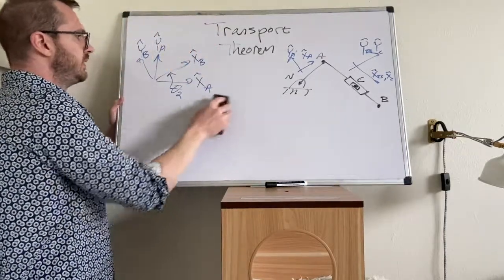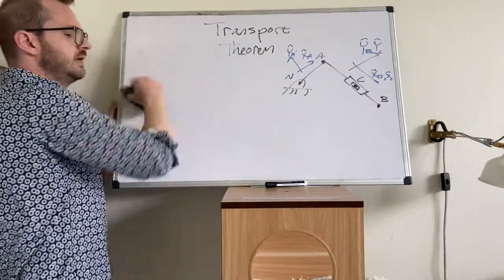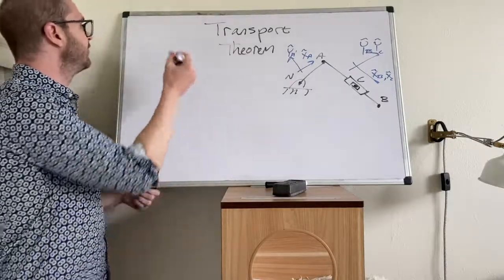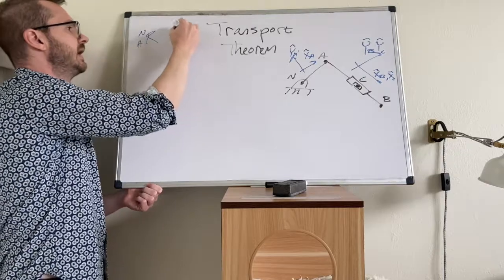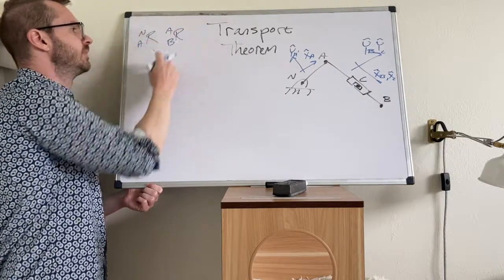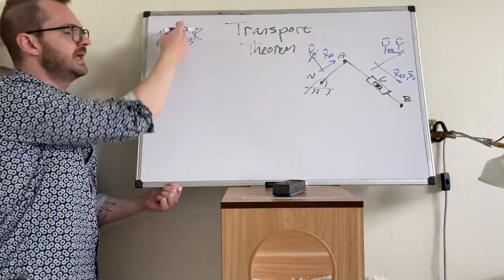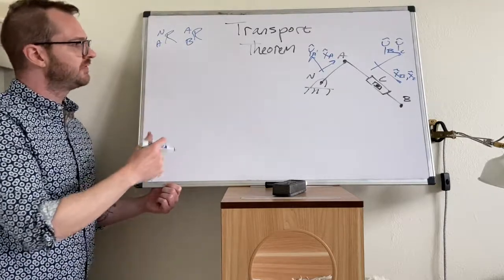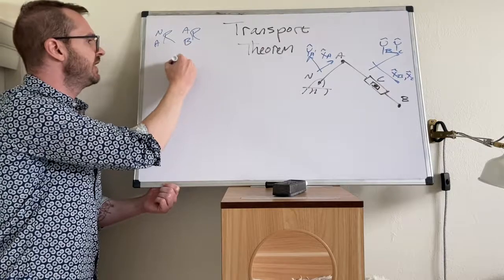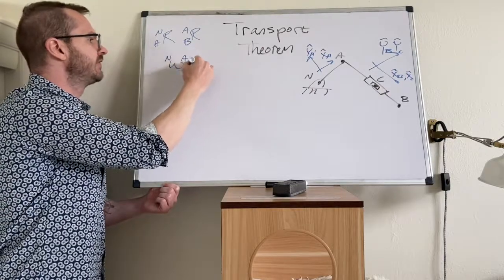Well, because we did relative angles, the two rotations that we defined were into A and A to B, noticeably different than into B. Before you do linear velocities, I recommend that you define your angular velocities.